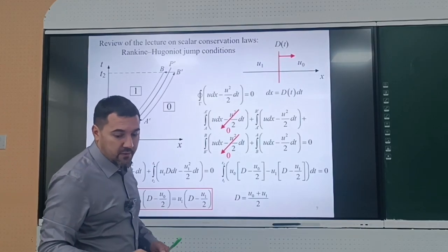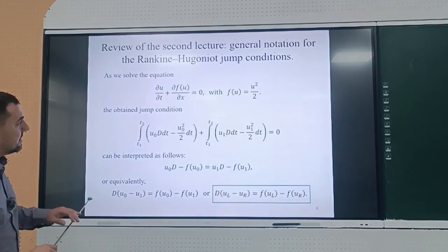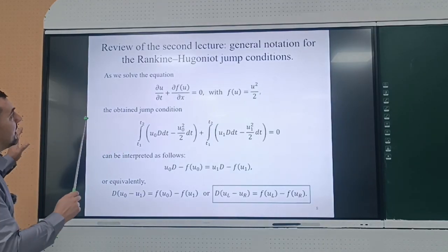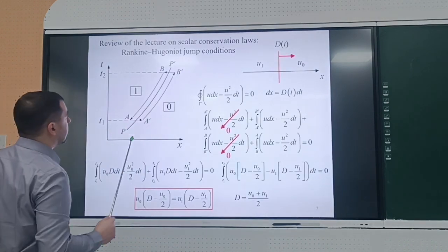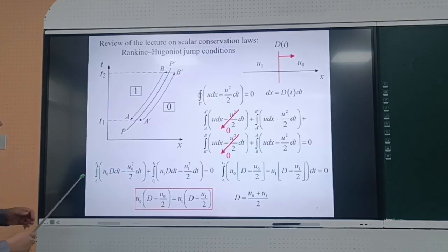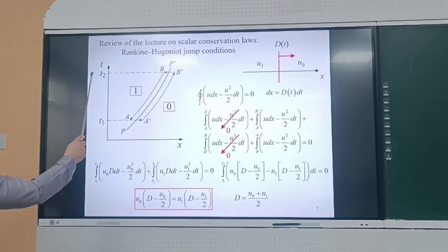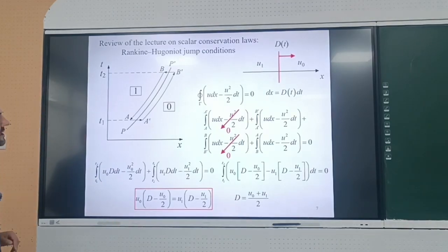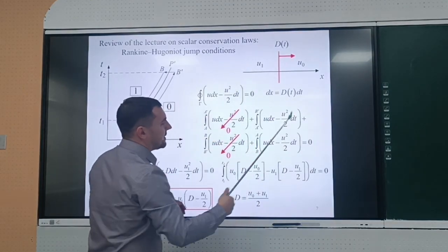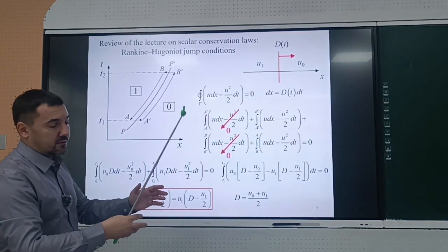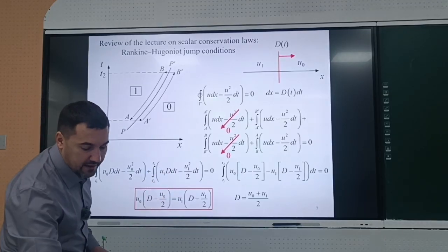What is also important for our lecture is that we named this formula the Rankine-Hugoniot jump conditions. Although Rankine and Hugoniot considered gas dynamics, and I will show it later today. But nevertheless, this is the Rankine-Hugoniot jump condition. It means that if you have a discontinuity, it's not possible to have arbitrary parameters on one side and the other side. They should be these ones.